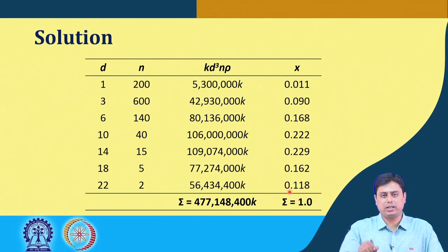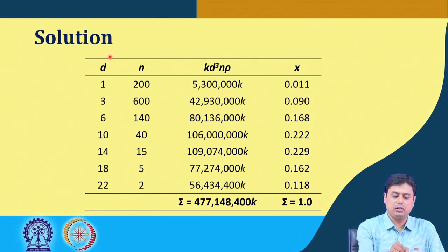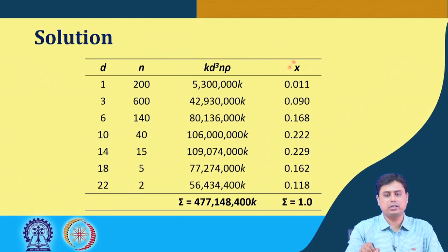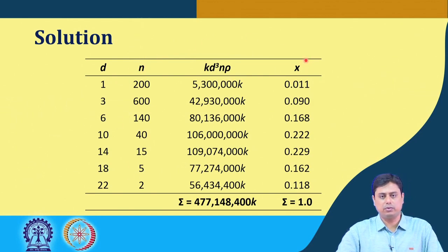This is the total mass fraction of the sample, which has to be 1, the summation of all mass fractions of all the individual particle size components. Okay. So, which means now we have the size range and mass fraction. So, eventually what we have done is converted this number distribution to a mass fraction distribution.